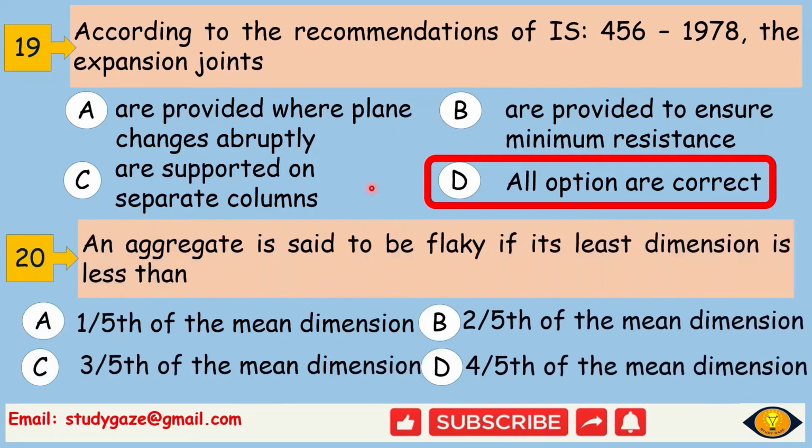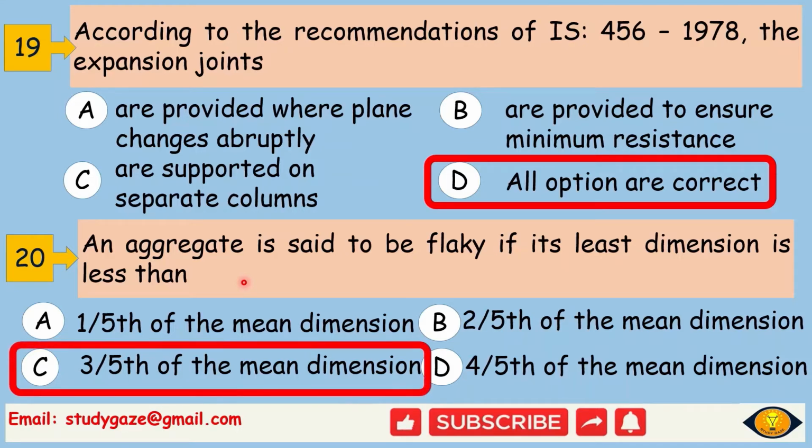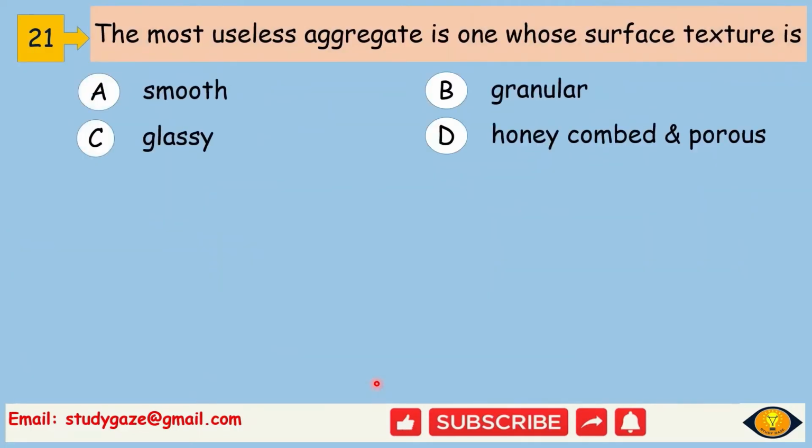Next, an aggregate is said to be flaky if its least dimension is less than. So the correct option is 3/5 of the mean dimension. If the least dimension is less than 3/5 of the mean dimension, then that type of aggregate is called flaky aggregate. Next, the most useless aggregate is one whose surface texture is.